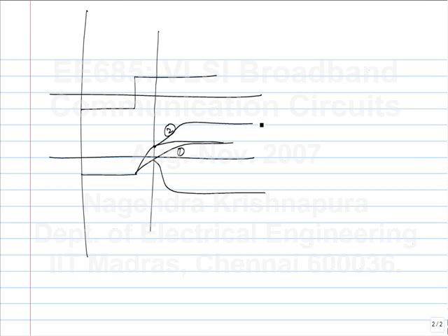But if you have to improve the setup time, this is the route that you have to take. And of course, like with any circuit, you will reach a point where the transistor's own parasitic capacitance will dominate the picture. So, at that point, you can't do anything. Given a transistor, its GM to capacitance and all of this is fixed, right?